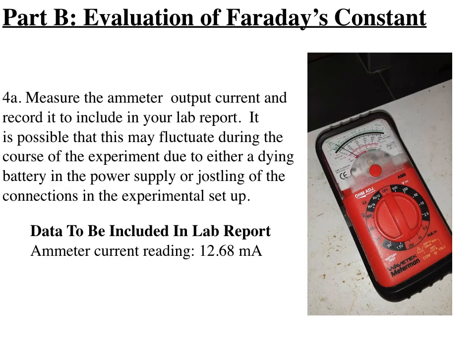Simultaneously to when I complete the circuit, I note the time at which the experiment has begun. When I complete the circuit by connecting the battery and meter to the two sets of terminals, I should notice a deflection on my ammeter dial indicating the amount of current that is flowing. Now, I should be very careful in monitoring this current because it could fluctuate during the experiment. It could lower due to a drop of the juice in the battery, or it could lower due to jostling due to handling during the experiment.